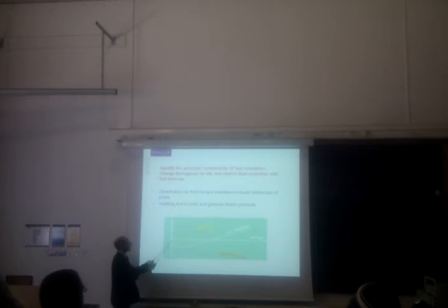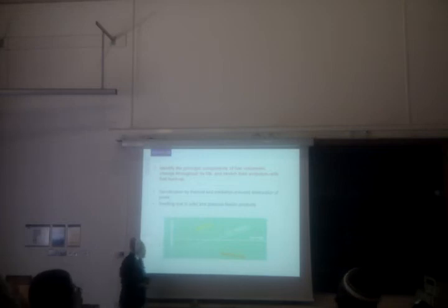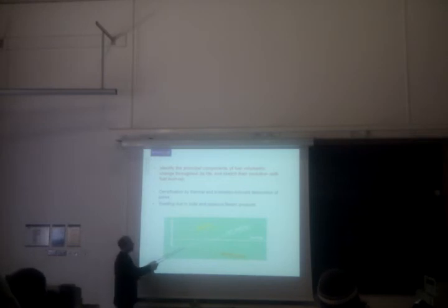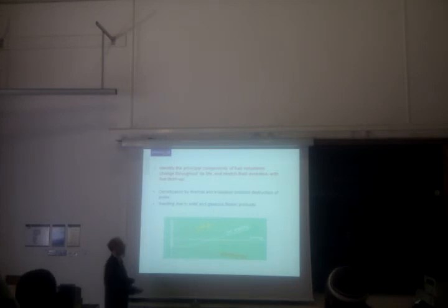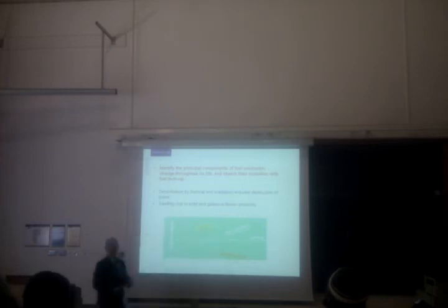higher. So this densification plot starts quite rapidly, but then tails off and becomes almost flat towards the end of life. The net swelling rate is just the addition of those two lines. So we get an additional shrinkage of the pellet. That shrinkage kind of stops, and then from roughly 8-9 months into the irradiation, we just get a net positive swelling rate. And at some point, the pellet's volume will become equal again to its original volume, and from there on in, it just keeps getting bigger and bigger and bigger.